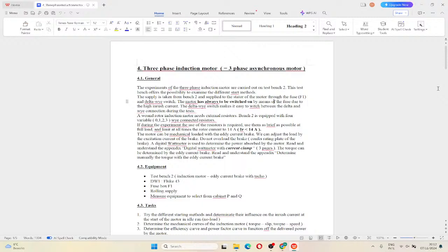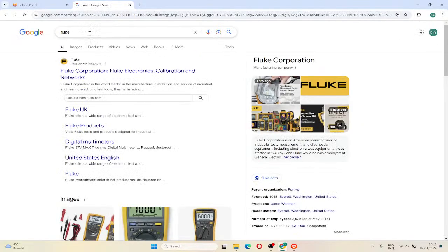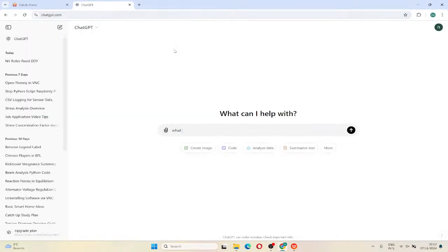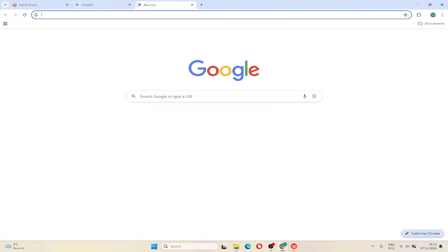Then we record all the values. Those P, Q, S can all be measured by the Fluke, right? You could always use the Fluke to measure those, P, Q and cosine phi. It's mentioned in the documents that we use the one watt-meter method by using the Fluke. So we can measure it, but we need to do some calculation. But the Fluke has the function to just get all the data as we need.